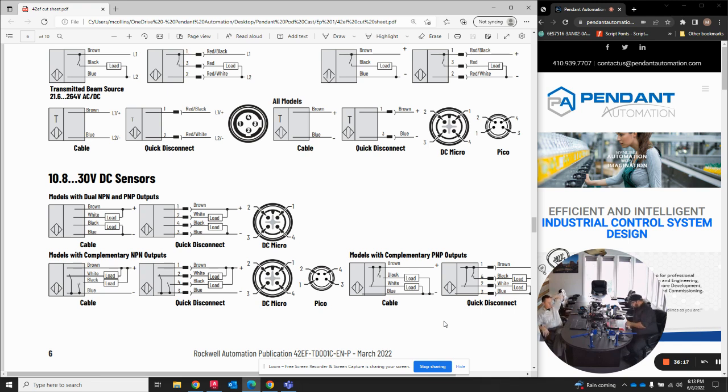I always had trouble when I first got into automation. I mean, it intrinsically makes sense to me now that NPN is a negative signal from the sensor and PNP is positive. But then somebody said to me, if you look at NPN, the P is interrupting the N. The N is being switched. And if you look at PNP, the N is interrupting the P. I mean, the P is being switched. Yeah, exactly. So every time I look at NPN and PNP now, I think, well, that thing's trying to be all P, and that N is kind of interrupting it on and off. So it is diametrically opposed from what should make sense, but that's my mental trick to remembering which one's which. Yeah, exactly. The P has more P, so it's positive. The N has more N, so it's negative.